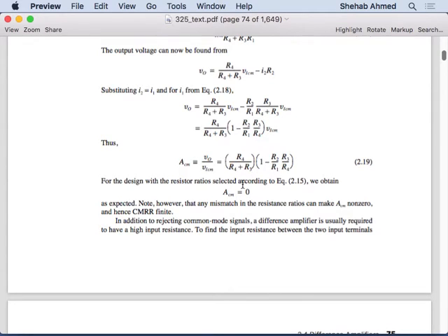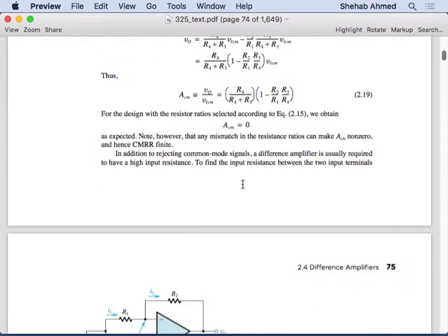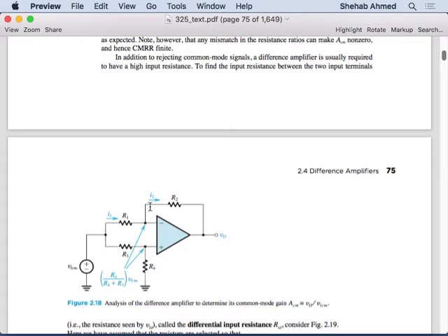We added this potential divider at the input. But the problem with that is these resistors have to be very well matched, which is very tough. You cannot buy identical resistors, nothing is identical to the other. It's a manufacturing process, there are always discrepancies and errors. So you can screen the resistors, and that's what happens when you buy more expensive resistors. It means that they're screened for their values, right?